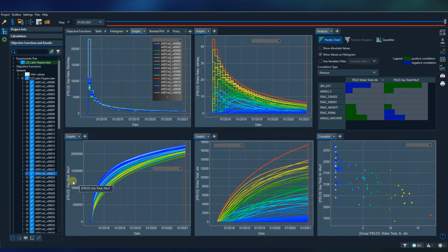The results show the impact of these parameters on the total gas and water production. So by analyzing this data, it can be identified the most appropriate fracture design to maximize the total gas production while maintaining low total water production. It could also be specified which parameters will definitely lead to more water being produced from implementing any sort of fracture geometry into these wells.